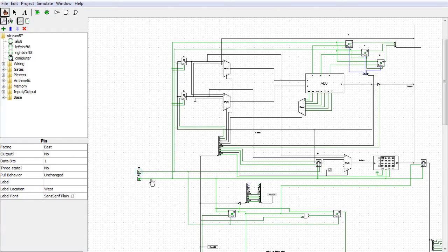It has to start on a rise. It has to start on a high clock. If it starts on a low clock, you're going to get an extra instruction executed before it's loaded. So it's going to execute opcode 00. No matter what you have here, it's going to execute. I'll demonstrate this later, but just know that you have to start on a high clock, and we'll fix that later.